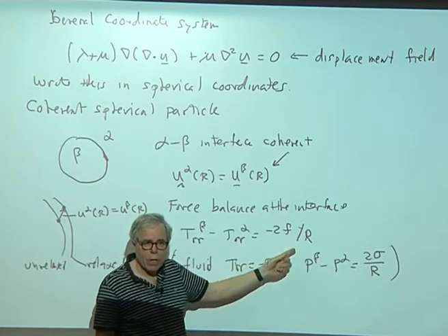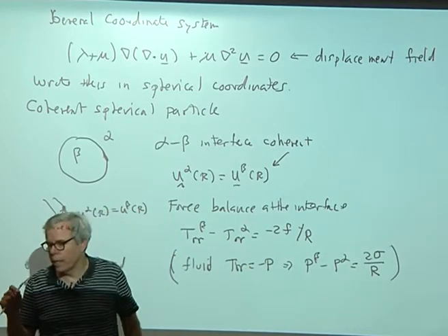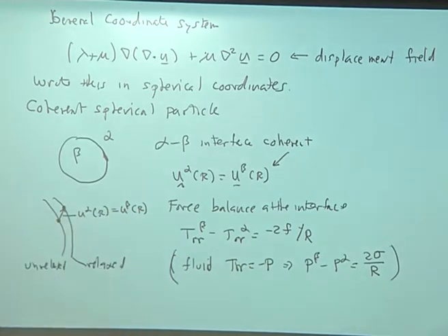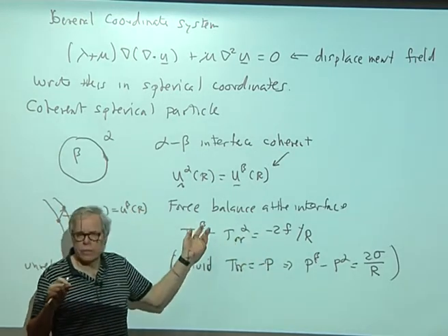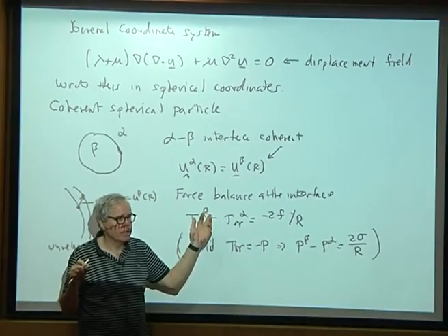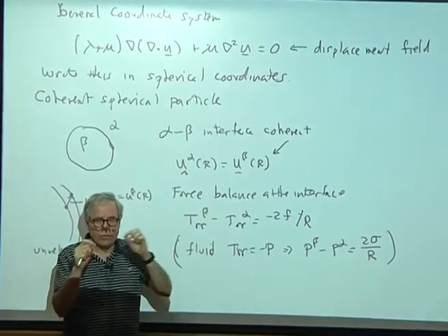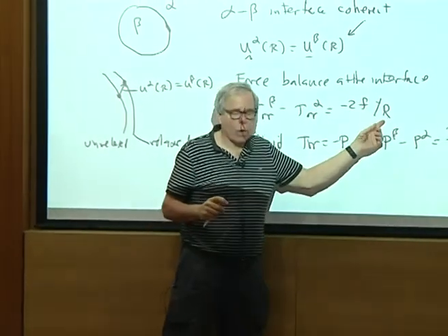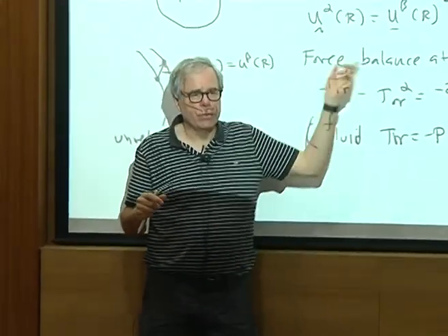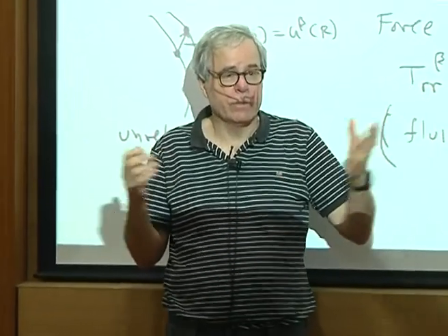So if you took a droplet or a particle that's on the order of 10 nanometers, 5 nanometers in diameter, with those kind of interfacial energies I just gave you, the stresses inside could be on the order of a gigapascal. So even though the surface stresses are very small, if I'm allowed to choose R small enough, these stresses can be big, gigapascals.